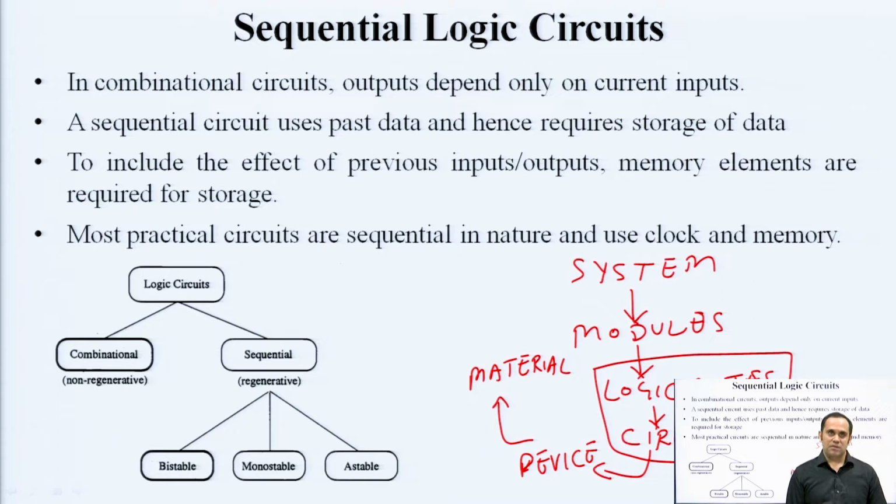Whenever we want, we can process the circuitry inside the combinational block and get the output. The input which is present at the time of processing is only considered. There is no role of the past inputs. There is no concept of memory, there is no concept of sequencing or clocking. So, combinational circuits are very simple and straightforward, but from the practical point of view, from the operational point of view, they have certain limitations. Although, for every sequential circuit you need at least one or more combinational blocks.